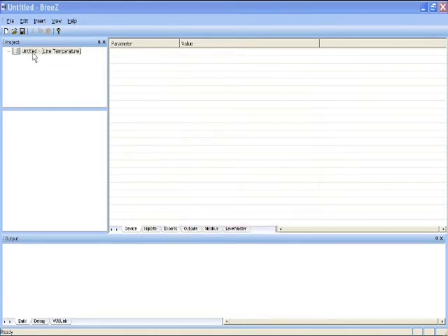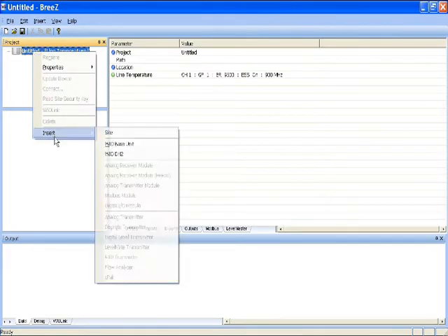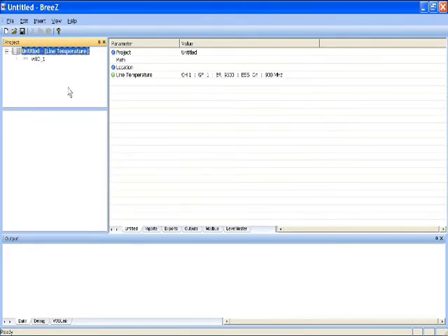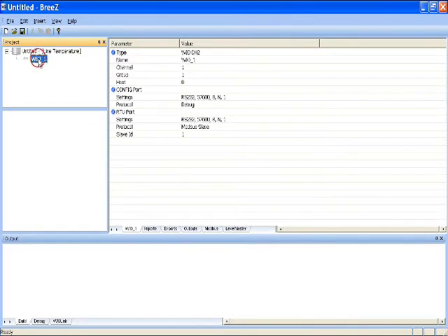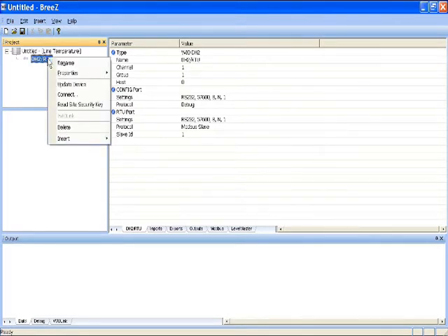Double-click on the name, right-click, and insert your first piece of hardware, a DH2. Double-click on DH2, right-click, and rename. Today I will name it DH2/RTU to signify that I am interfacing to an RTU. Then right-click on DH2, go to Properties, Edit.